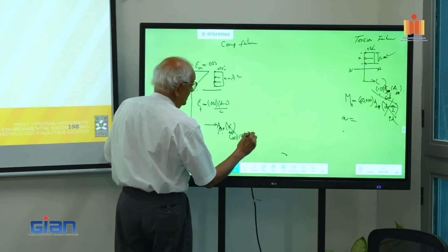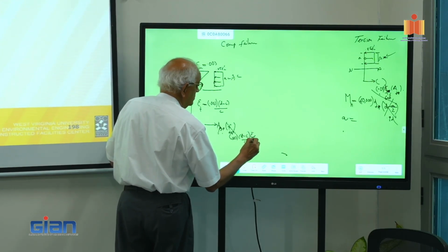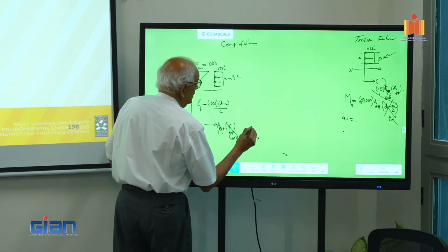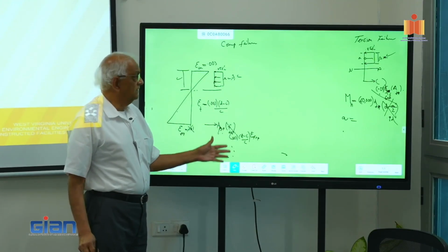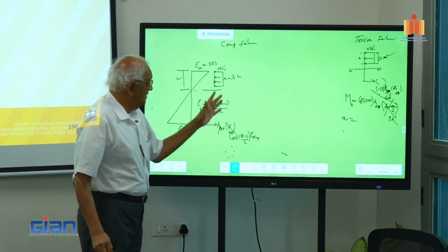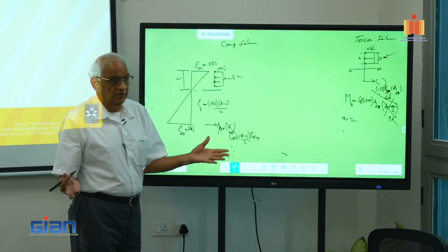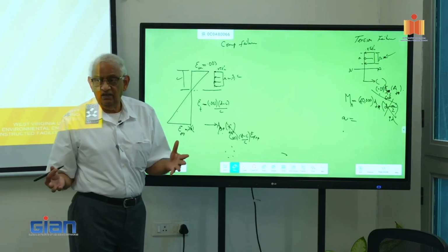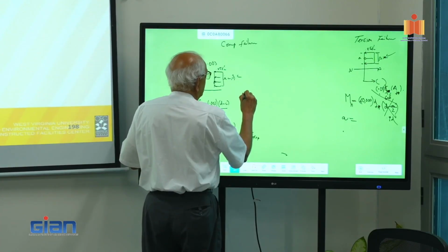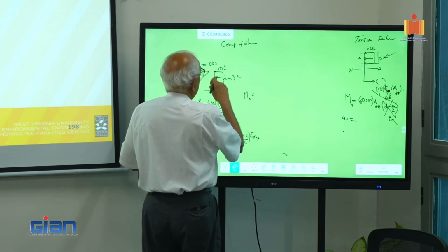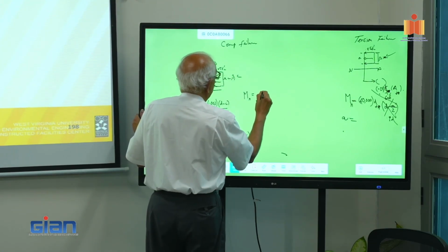That is the strain, you multiply it with E_FRP. So this should be equal to this, that is the equilibrium part of it, and you substitute. From this equilibrium, we are now trying to find c, which turns out to be a quadratic equation. Once I know c, the equation for M is essentially going to be the same, except you are going to look at it from the standpoint of whatever that 0.85.